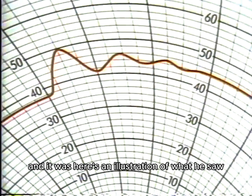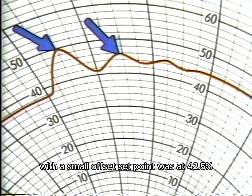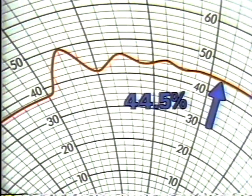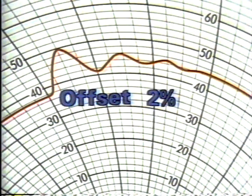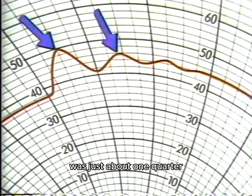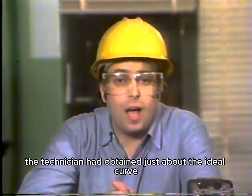And it was. Here's an illustration of what he saw when he had the gain adjusted correctly. A characteristic quarter decay ratio curve with a small offset. Set point was at 42.5%. The new control point was 44.5%, producing an offset of 2%. The ratio of the height of this peak to this one was just about 1/4. Except for the 2% offset, the technician had obtained just about the ideal curve.